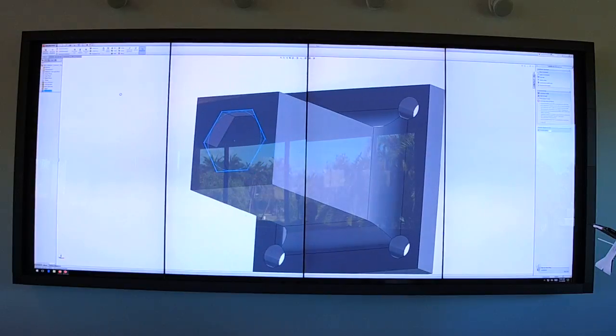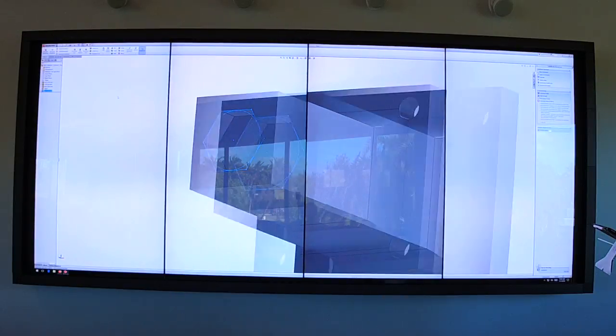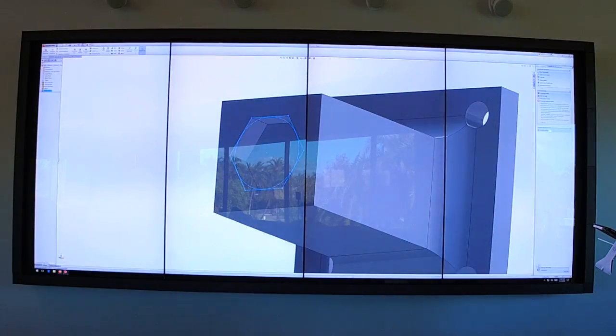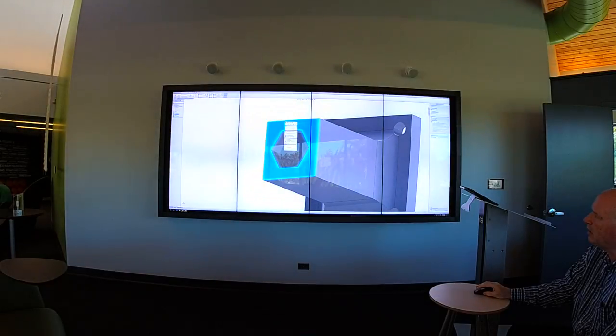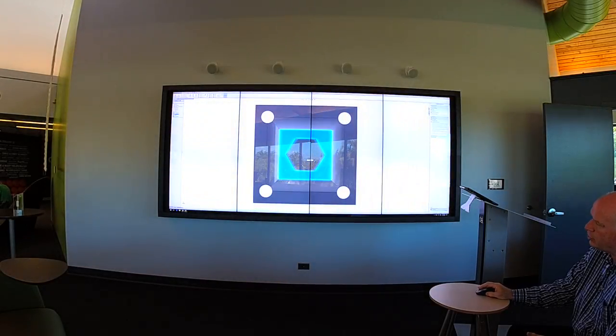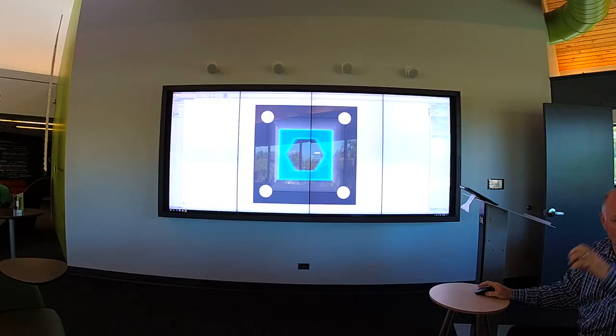So what we've now got is a 5 millimeter hole. When we talk about a nut trap, I'm going to put a metal bolt in there, and that nut is going to sit in that little trap, and when I tighten it up from behind, it's going to hold on really tight. So again, what we've got here, let's come to the face on that, is a nut trap, but we need a hole. We need the hole for the actual thread.